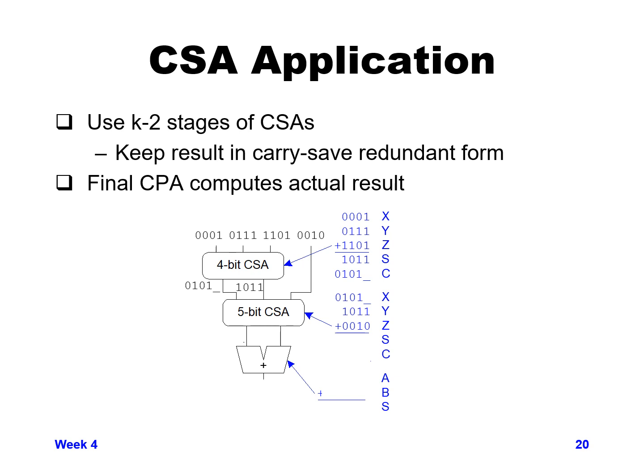But if we now send that into a 5-bit CSA, because the carry is shifted, so we need an additional bit, we can send those 2 values in along with our 4th data value as our bits 4 through 0, or 5 through 1, depending on how you want to do your bus notation. Then we'll get out of that 5-bit CSA an additional C and S that are 5 bits worth. Again, the carry is shifted relative to the sum by 1 bit.